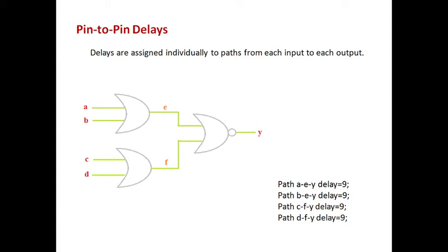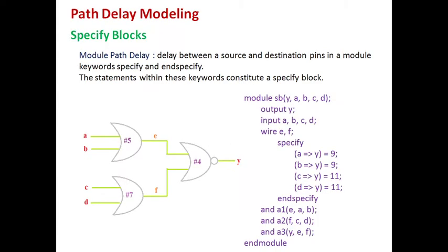This path delay has tremendous usage, which you will see in the succeeding sections. So let us discuss those things here. According to path delay modeling, we need to cover certain terminologies like specify blocks. Inside the specify blocks, there are full connection as well as parallel connection. We need to focus on these terminologies also. So what is a specify block?